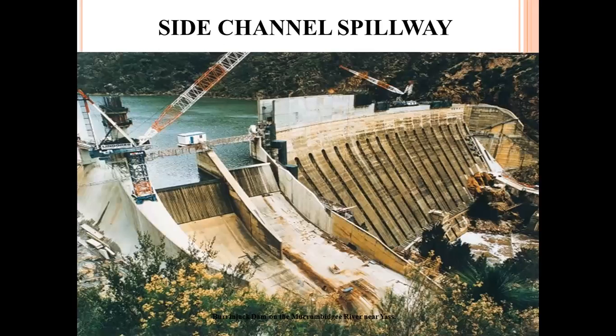So you can see this is the original dam, but here the spillway is not provided. Instead, they are constructed at the sides of the dam. These are the side spillways, so it is a side channel spillway. The water is released from upstream to downstream through these two channels, not from the dam. The dam acts as a barrier wall, a retaining wall.